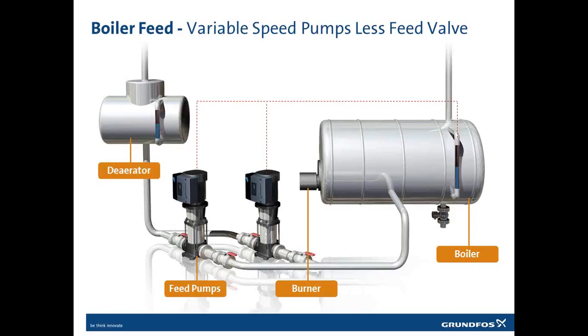You have to set up the strategy in the controls to protect the pumps, so that they're not running against a closed valve, and there's always water moving through the pumps. Yes, exactly. That's also why I recommend using the CUE. Of course I do that because it's a Grundfos product, but it has the right solutions for doing this system.